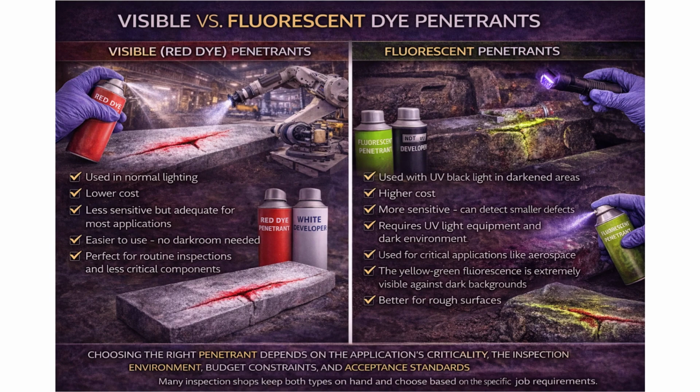Before we wrap up, let's talk about safety and best practices. Personal protection. Always wear appropriate gloves when handling penetrants and developers. Use safety glasses to protect your eyes. Work in well-ventilated areas. Some chemicals produce fumes. Avoid skin contact and never ingest these materials. Environmental considerations. Properly dispose of used materials according to local regulations. Many penetrants contain chemicals that require special disposal. Don't pour them down drains or into the environment.